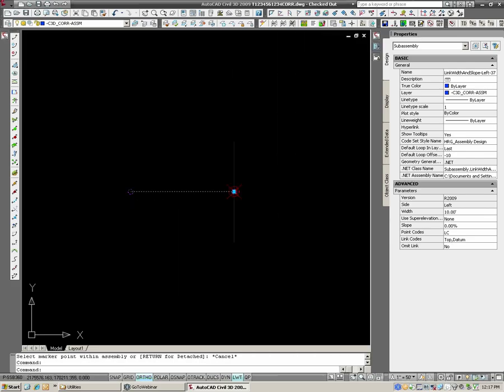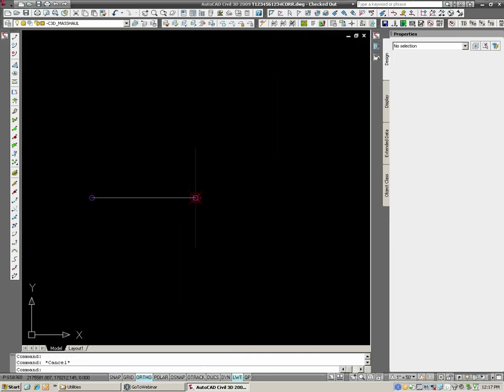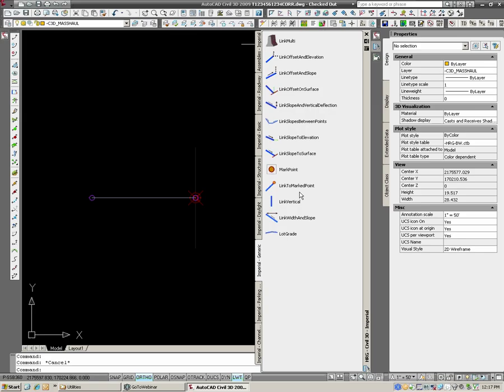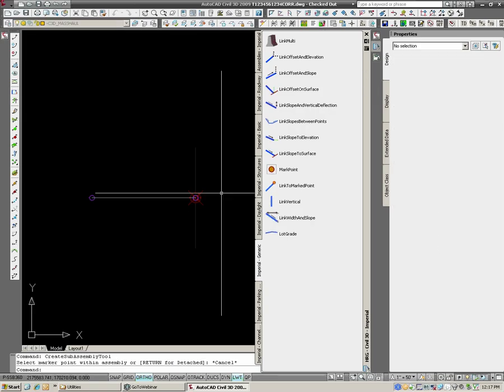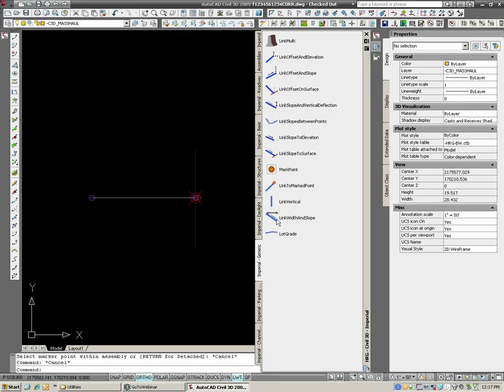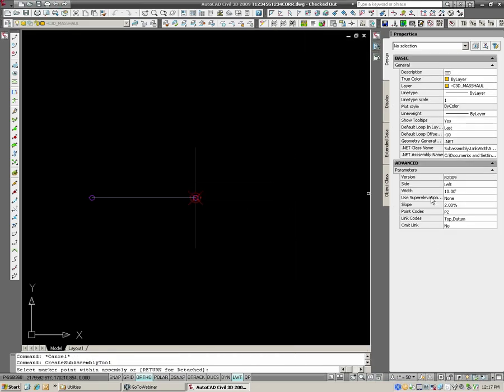Now, if I hadn't hit enter and played around with opening my properties dialog box, all I would have needed to do is just switch it to right. But since I messed around with some things, I'm going to have to go ahead and click that again. And in here, I'm going to need to change the side now to right side. I'm going to do 0 again.